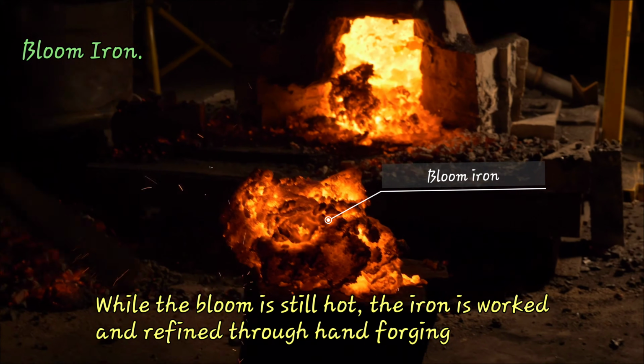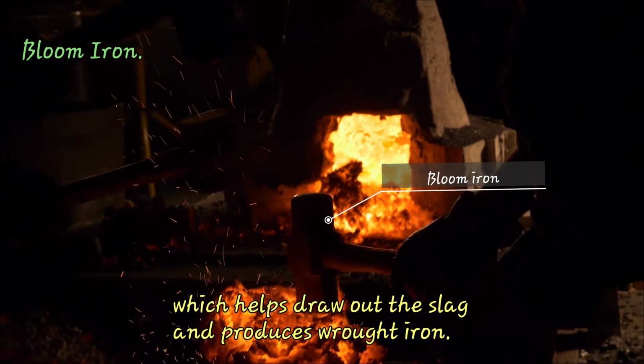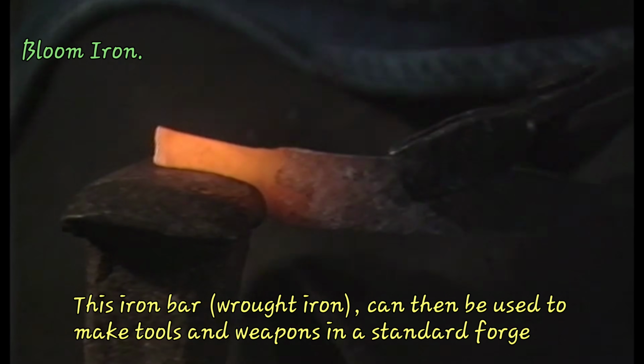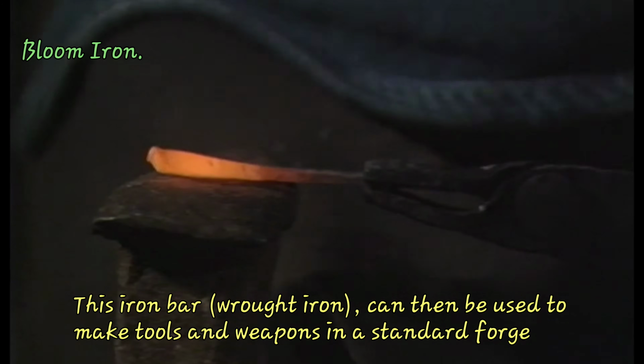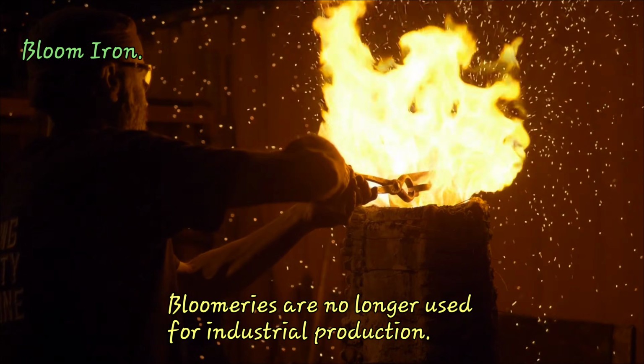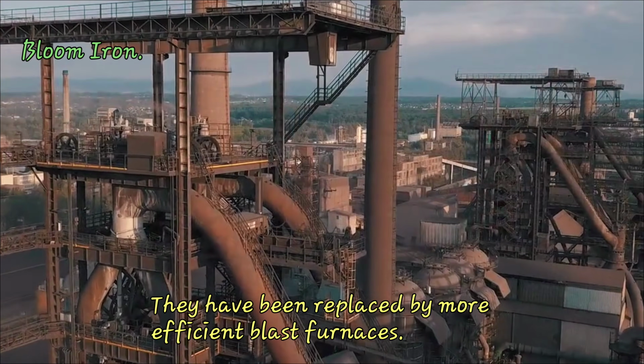While the bloom is still hot, the iron is worked and refined through hand forging, which helps draw out the slag and produces wrought iron. This iron bar, wrought iron, can then be used to make tools and weapons in a standard forge. Bloomeries are no longer used for industrial production. They have been replaced by more efficient blast furnaces.